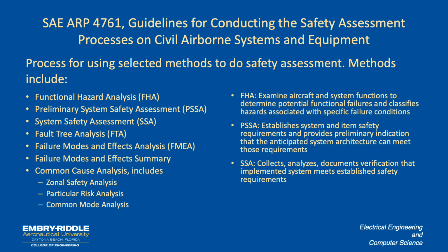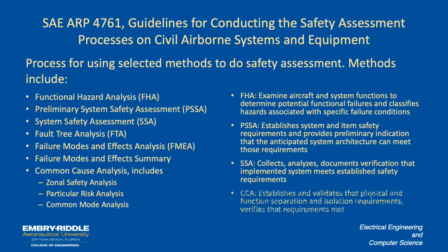And then there's a common cause analysis. And this includes what's called a zonal safety analysis, particular risk analysis, and common mode analysis. And so the common cause analysis establishes and validates that the physical and functional separation and isolation requirements are there, and it verifies that those requirements have been met.